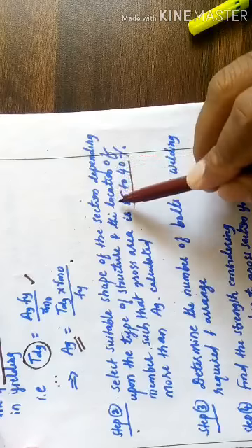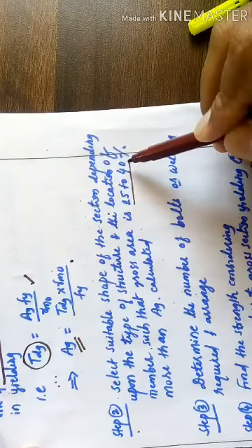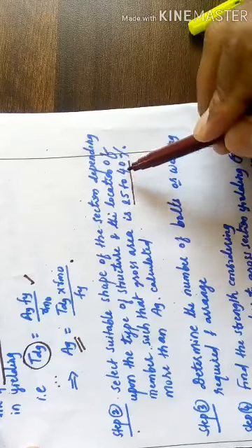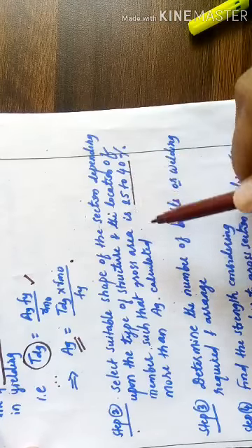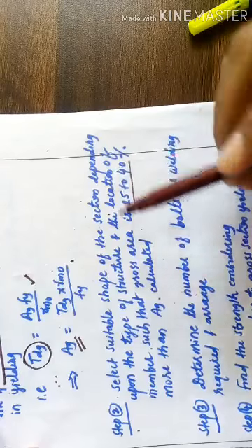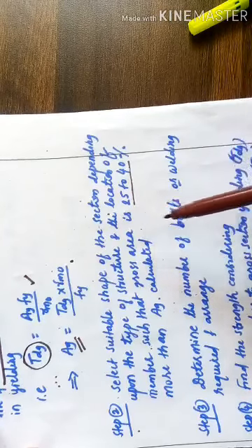This is just a factor of safety. On the safer side, the area needs to be increased by 25 to 40%, and the section is selected from the steel table for that increased area.